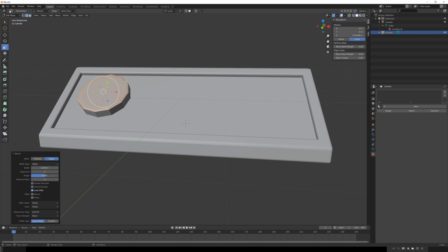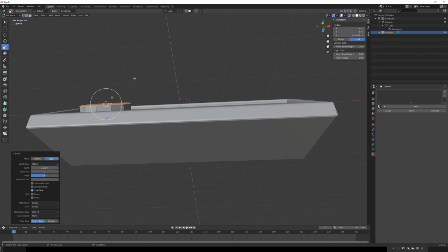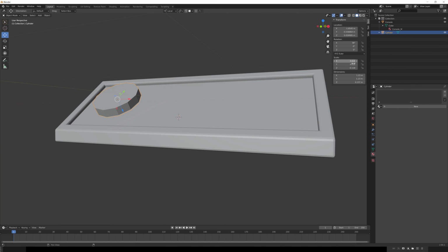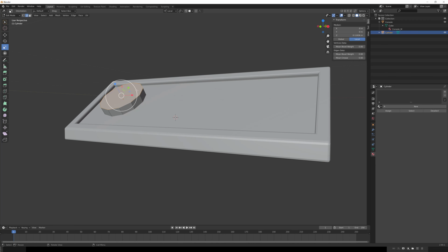And here you can see what's going on, but once again that bevel looks kind of off. Whenever we see tools seemingly not working properly, all we have to do is go in and check our scales. And once again, notice that we have almost a 6:1 scale ratio on these different axes. So hit Control and A. I'm going to go ahead and apply scale in this case. I'm going to leave the rotations as they are. Hit the Tab key, right click again, hit Bevel Edges, and there we can see that it's acting far more appropriately.